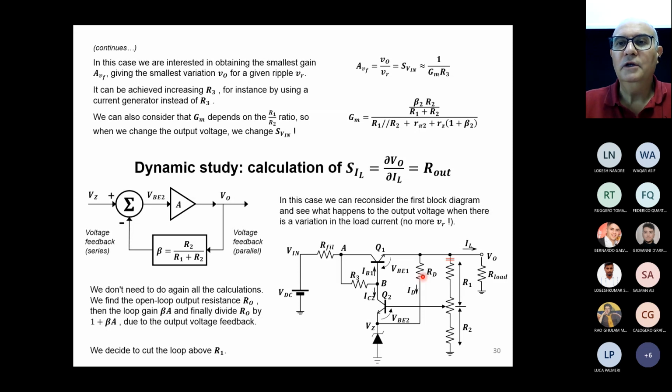One point where we can open the loop is here. You see there's two red lines, two cuts there. Why am I going to open it here? Because basically, if I disconnect this point, the total resistance that is seen by this point, if I look into this direction, is very high. It is high because basically it's given by those two resistances, more or less.